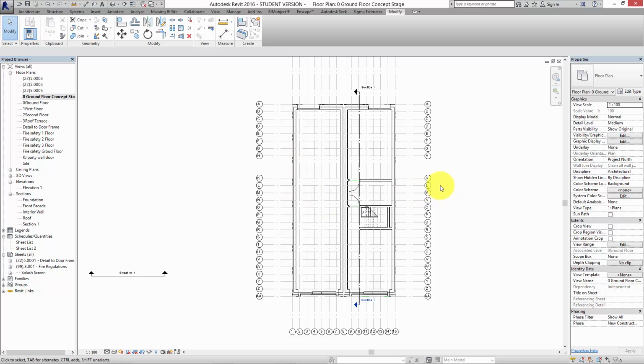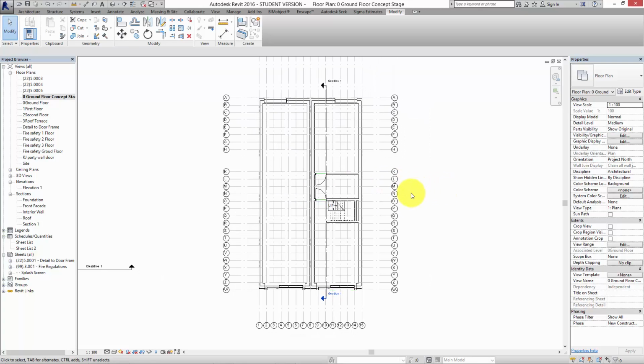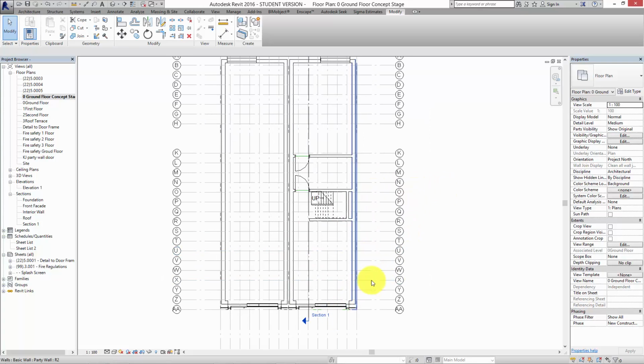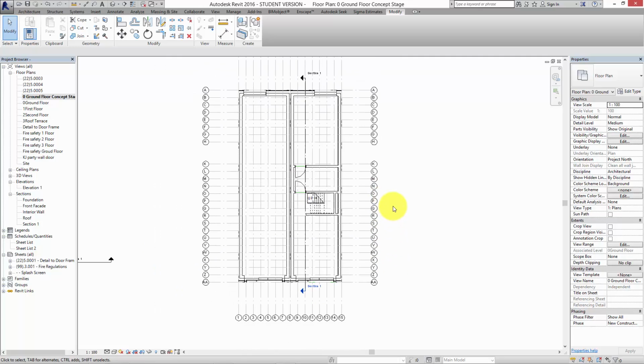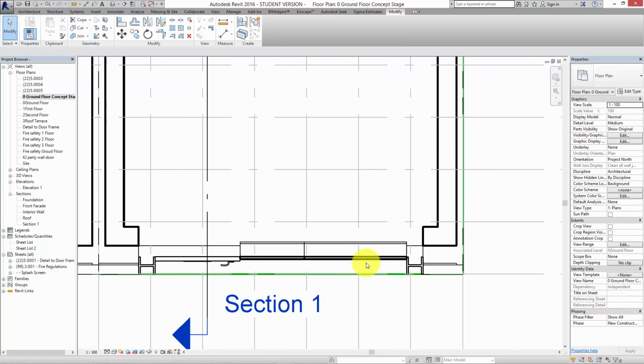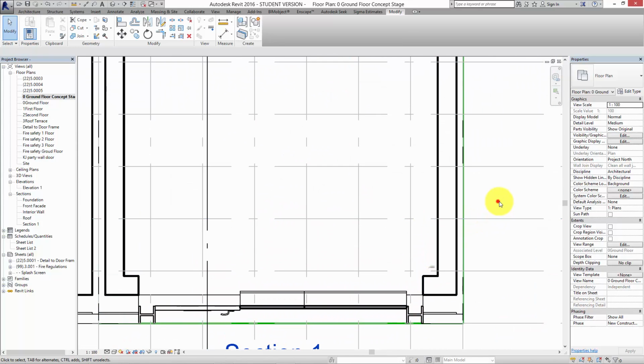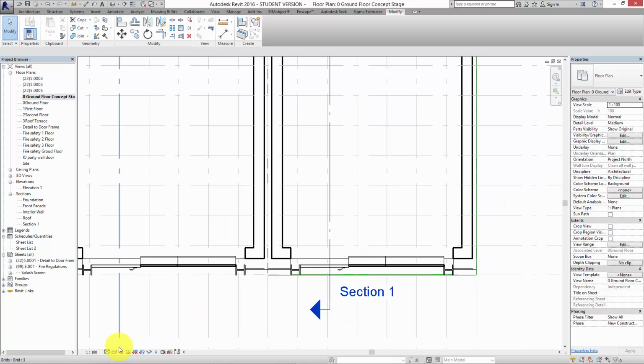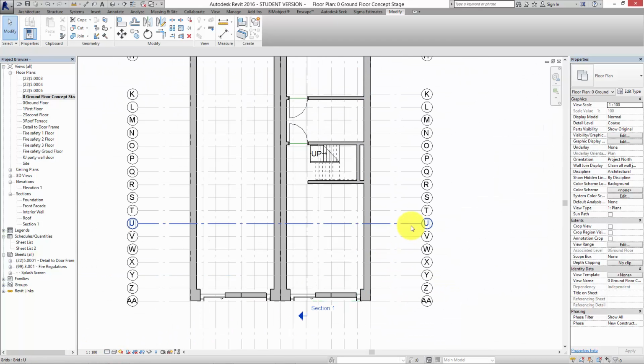So if it's ground floor concept stage, it's all about the house itself, the actual spaces inside it. We need to fill it up with furniture, we need to give floor areas, and we need to take any constructional detail out of the walls. All these cavity walls and so forth, the client doesn't want to see. So the quick way of doing that is just to change the level of detail down here. I could press this detail level, too coarse, and it just makes walls like that, okay?